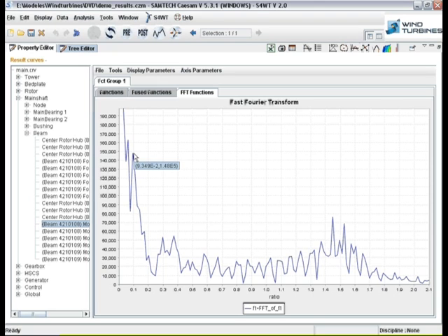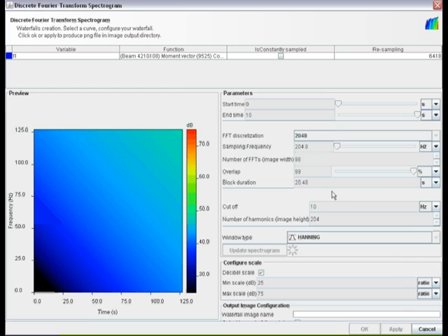A basic FFT transformation gives you the global frequency content of a signal, but it's possible that some frequencies were excited during a short period only, while others that were not showing at the time participated later. This is especially true in the case of an emergency stop. To obtain this information, one can use another powerful tool called waterfall diagrams.